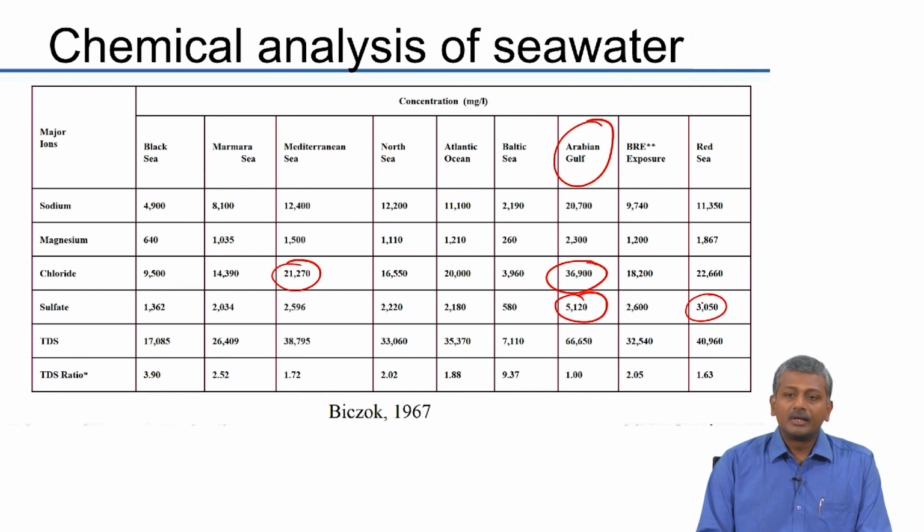So, irrespective of what type of mineral admixtures that you end up using, the commonly available mineral admixtures, either calcined clay or slag or fly ash, most of these will contribute reactive alumina which may end up binding the chloride ions. So, apart from the C3A from the cement, there will also be reactive alumina available from mineral admixtures that will end up binding the chloride ions. So, obviously, you will have a positive effect whenever mineral admixture is used as cement replacement in marine environments.